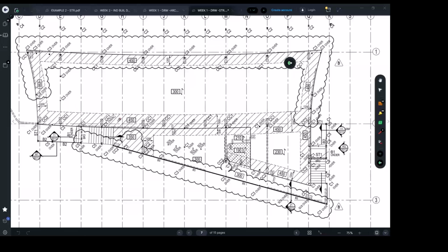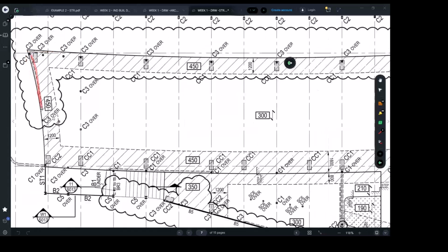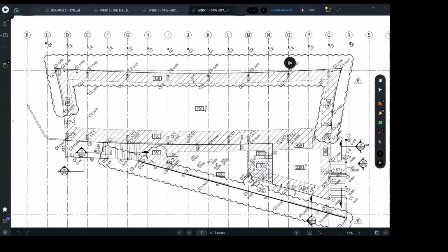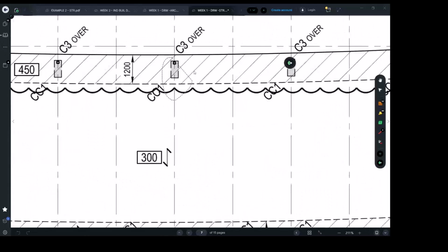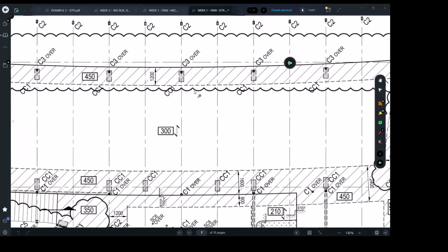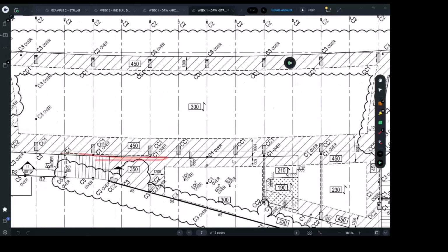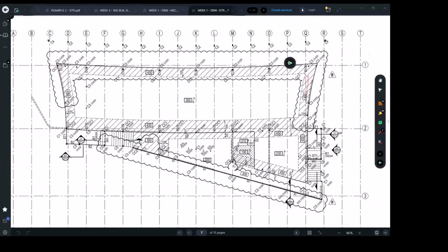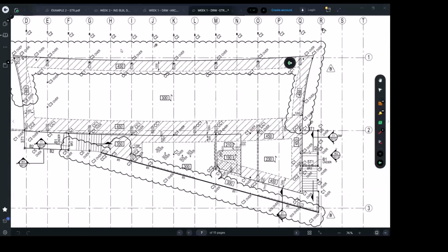So another character is that this building or this floor is stabilized by a block wall system. What really stabilizes it if we need to worry about lateral loads? We can't only rely on sticks, columns going out from the ground. Maybe the engineer did, but you can tell from the drawings, we have those walls, right? The hatched lines, like this line, this one at this end. You've got another element here. They are block shear walls. All right, so you can say the slab is laterally resisted by a reinforced block wall.